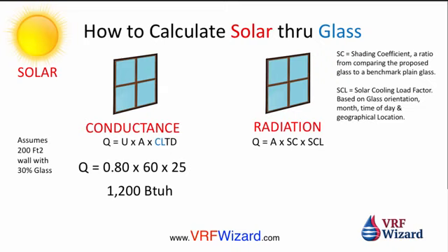So remember, the lower that U factor, the less load you're going to have on your building. Those real good glasses that they're developing now are going to reduce this number, which is going to reduce the BTUs that get through your building and have to be taken care of by your cooling system. So good glass will go a long way here.